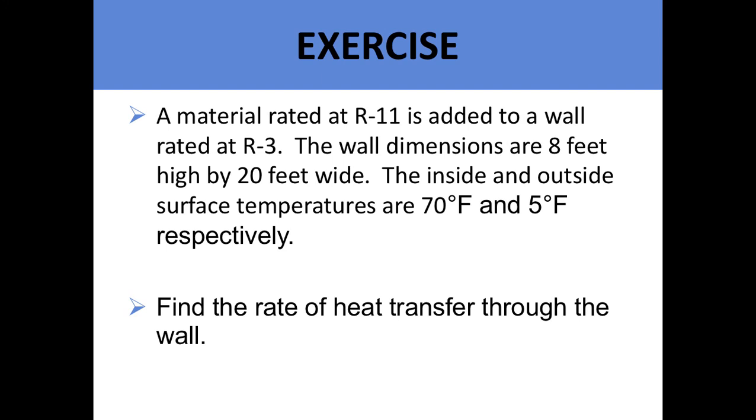A material rated at R11 is added to a wall rated at R3. The wall dimensions are 8 feet high by 20 feet wide. The inside and outside surface temperatures are 70 and 5 degrees respectively. Find the rate of heat transfer across the wall.